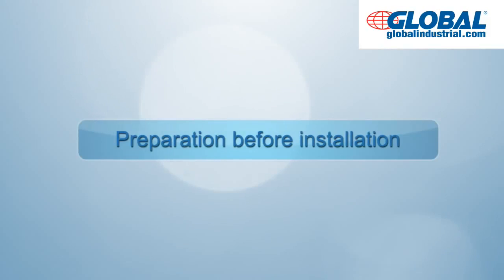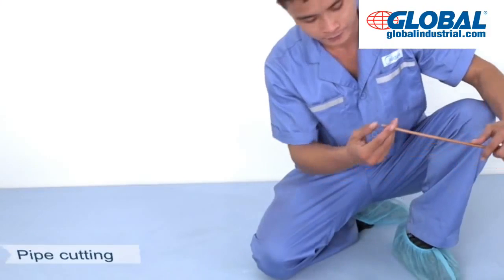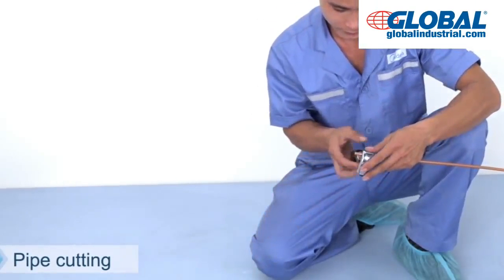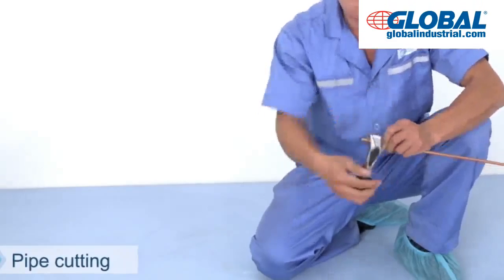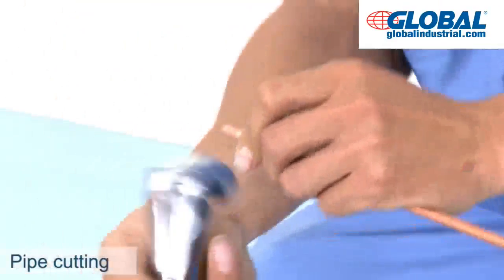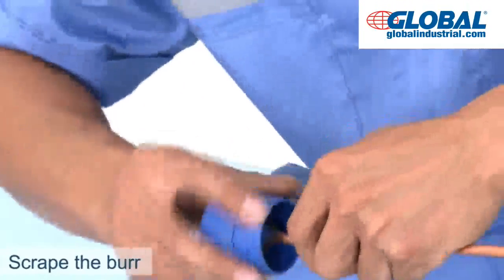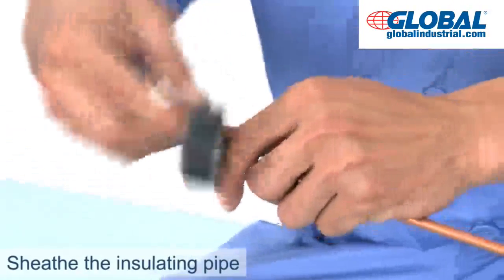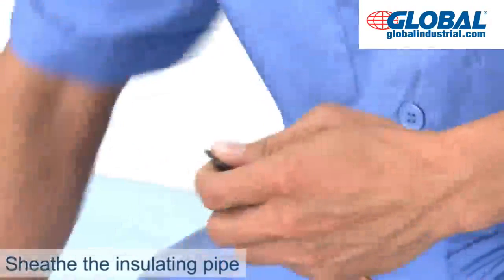Preparation before installation. Pipe cutting. Cut the suitable length of copper pipe as required. Turn pipe cutter slowly and keep increasing force gradually. Make sure there is no deformation. Cut surface should be level. Remove burr side of copper pipe with scraper. Use rubberized fabric to wrap copper pipe head to prevent foreign materials from entering.